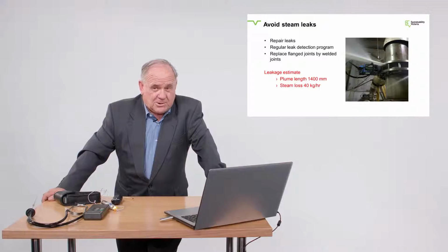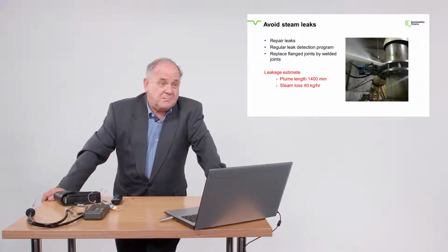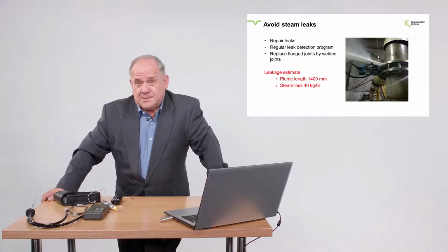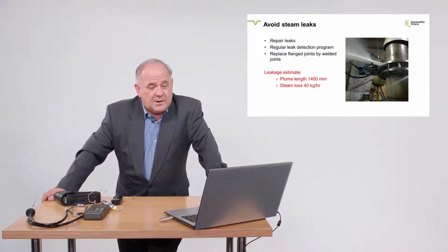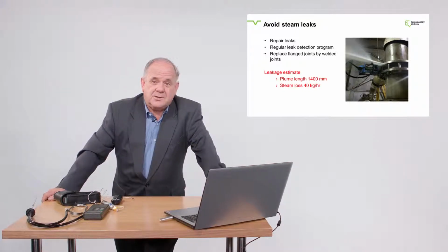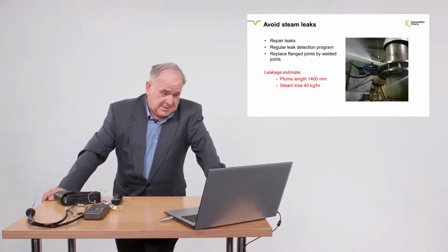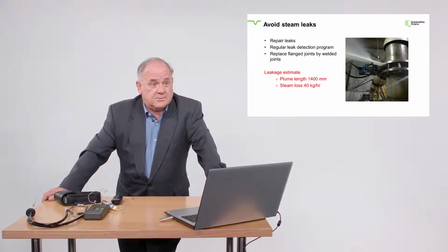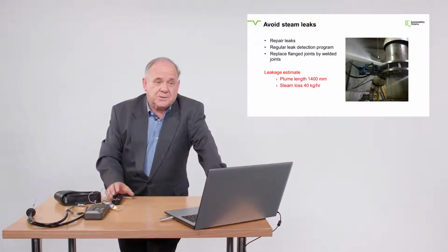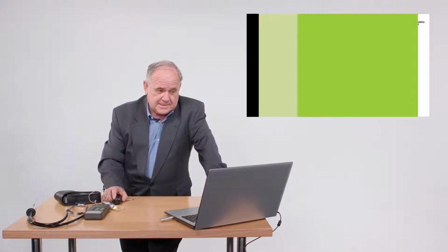So there's no reason, unless you can't get at the steam leak. There might be a production line, for example in a paper mill, where you can't get access to the steam leak because it runs 24/7. There are online systems where you can pump compounds in, still run the plant at high pressure and do semi-permanent seals if you can't shut the line. So a lot of people in the chemical and paper industries use those processes for very high pressure systems to fix the leaks while the plant still runs. So there's no real excuse for not fixing steam leaks.